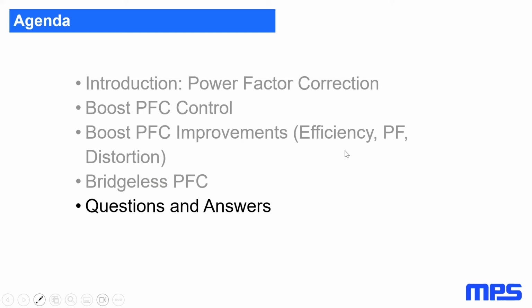So it might also be needed in totem pole, or it might be possible to get away with it. The good thing about the totem pole PFC is that you always have a switch in series. So if you control that switch, you can actually make a slow inrush current limiter. So depending on the complexity of the controller, you might be able to not have that bypass diode. It really depends on the implementation of the controller.